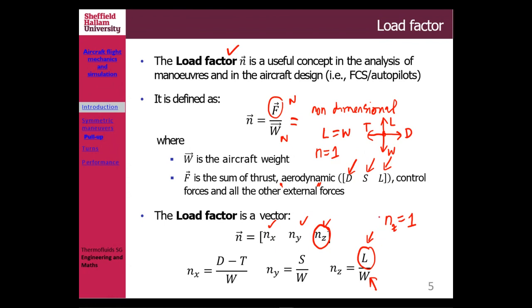Now, of course, this parameter we can put as a constraint when you design an aircraft. So in aerodynamics and perhaps from the aircraft structure point of view, we use a visual representation termed the flight envelope. Later on, we will talk about the flight envelope, which defines the operational limit for your aircraft with respect to maximum speed.